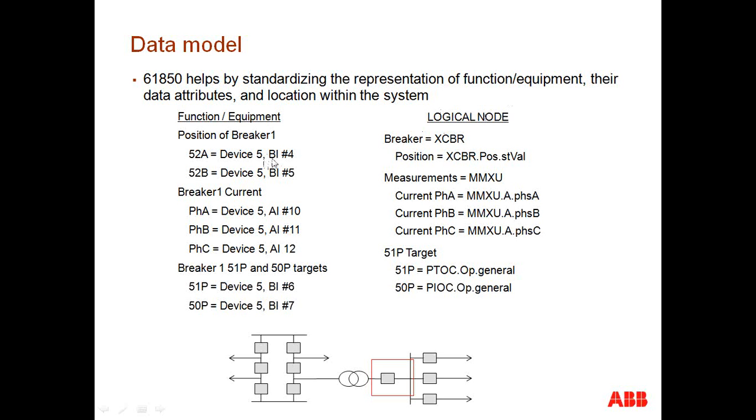Well, in 61850, there's no binary input, there's no analog inputs, there's no counters. The information is presented within the context of the application. So if we're going to talk about the position of the breaker, we're not going to talk about a binary point. We're not going to talk about a digital point. We're going to talk about the position of the breaker.